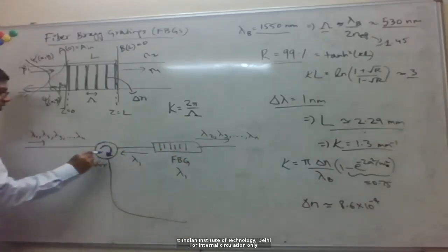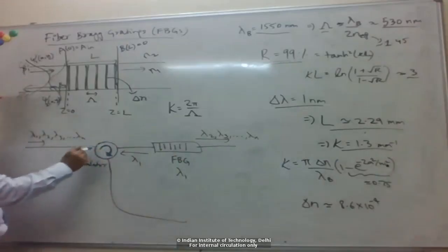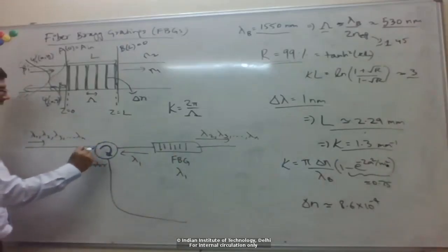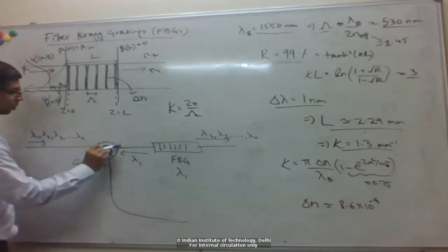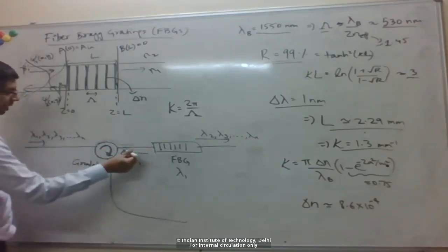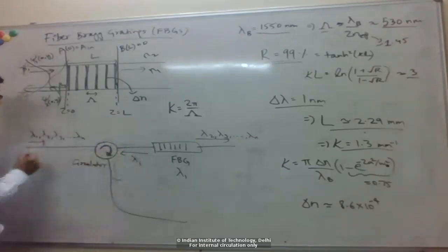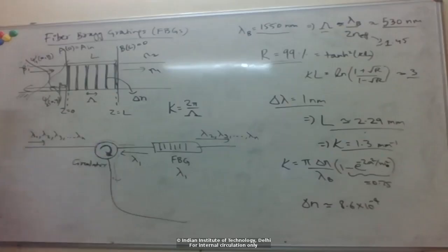So you can build these isolators which only let light pass one way. Based on that, this is like a 3-port device based on this optical isolation. So it only allows light to travel in one direction. Okay, so if we have light coming here, it will only go here. But if we have light coming here in the backward direction, it doesn't go back. It goes to the 3rd port. So light travels in this clockwise direction in the circulator. So if you send from here, it will go back here.